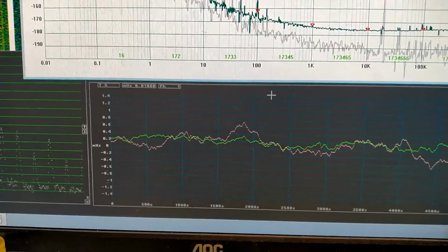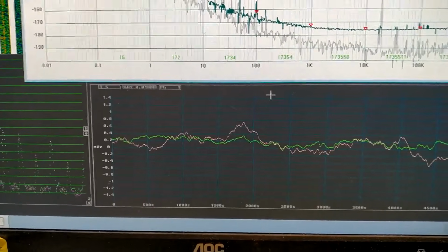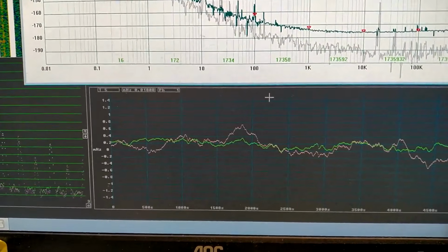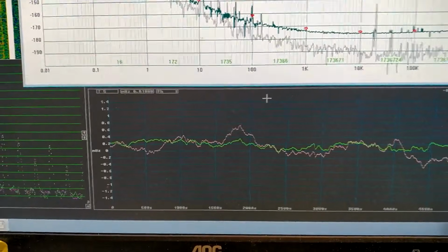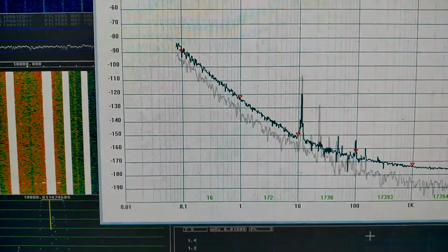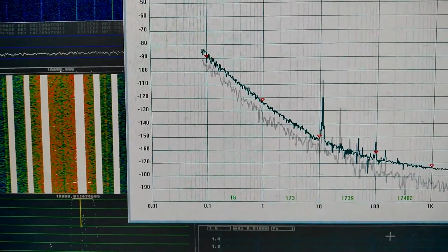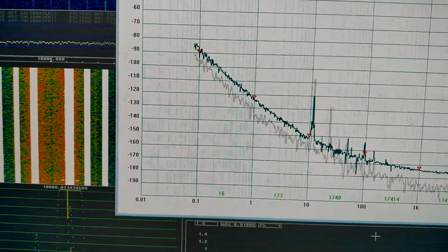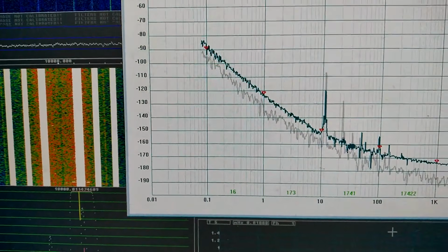And it looks like I have a too long time constant there. I will reduce it, I think, by a factor of 4 could be reasonable. This time the phase noise at 1 Hertz offset is minus 122 dBc per Hertz. So I guess the previous time there was some noise event.